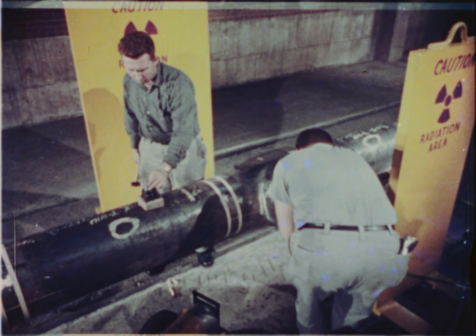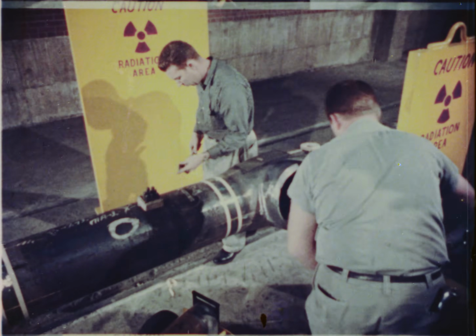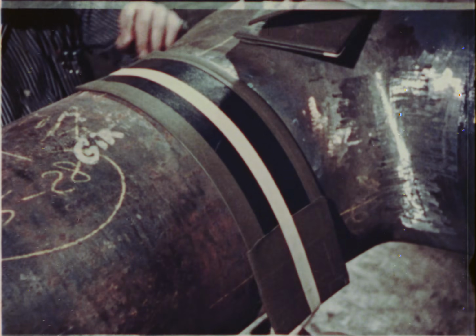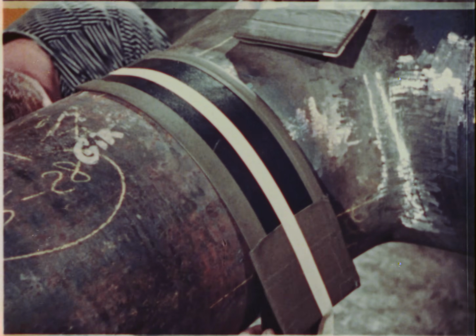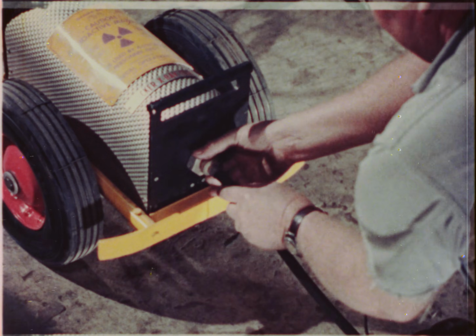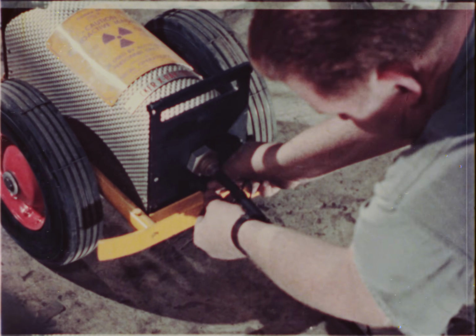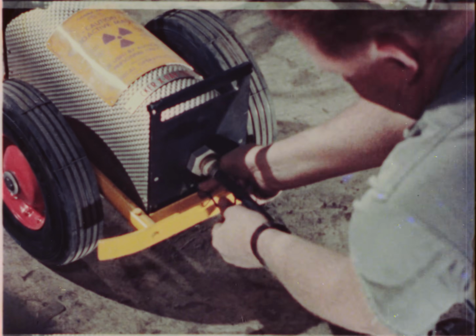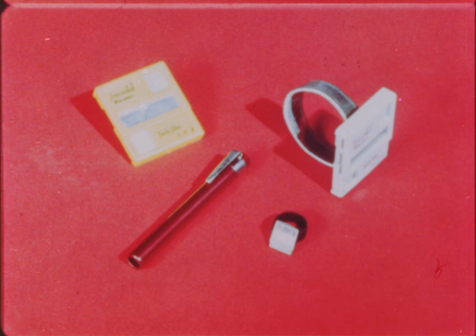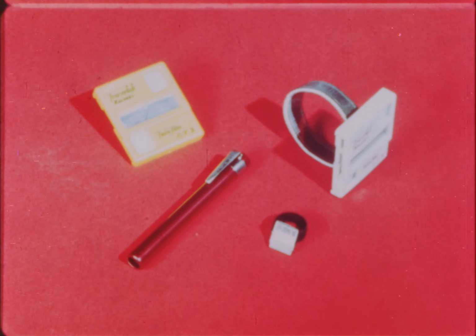Because gamma rays are needed to penetrate heavier, thicker material, the levels of radiation are usually higher in radiographic work than in other applications of isotopes. Therefore, more exacting safety procedures are employed. Standard safety devices such as survey meters, dosimeters, and film badges, together with adherence to common sense rules, help to ensure accident-free operations.